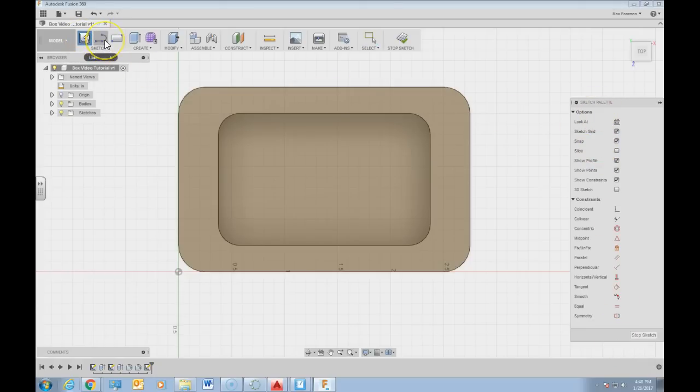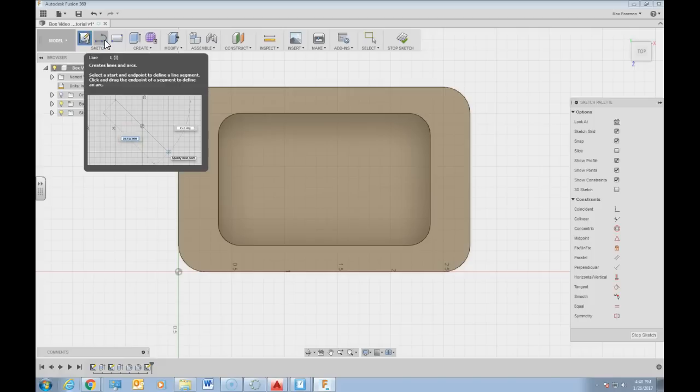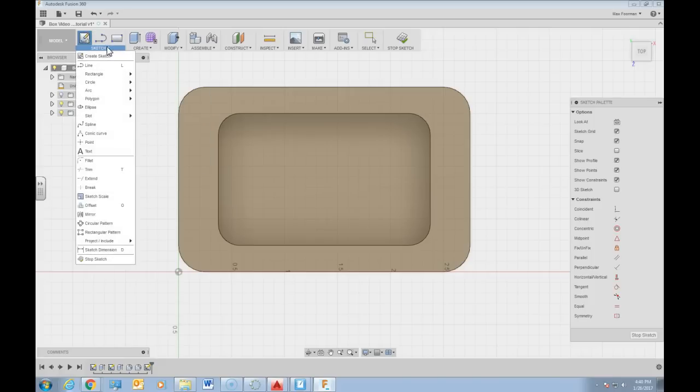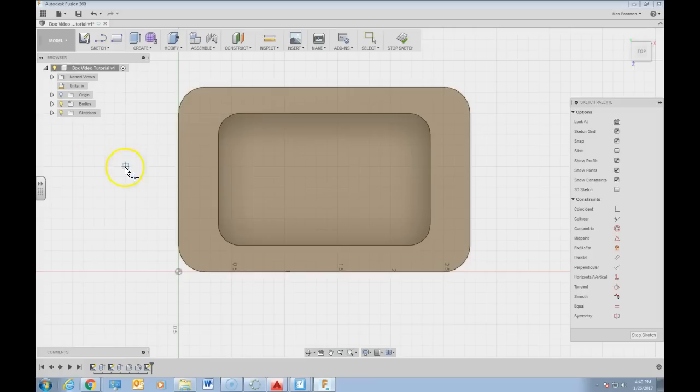I'm going to create sketch. Whoops, excuse me, I did that already, so we don't need to create sketch again. We're already there. Sketch right here, come down, clicking on this Point. It creates a sketch point. Exactly what we want. Now we don't have to be super concerned with where we're clicking. It'll snap to these points. That might be where we want it, might not. So we can try clicking right there. Okay, for right now I only want that one single point.